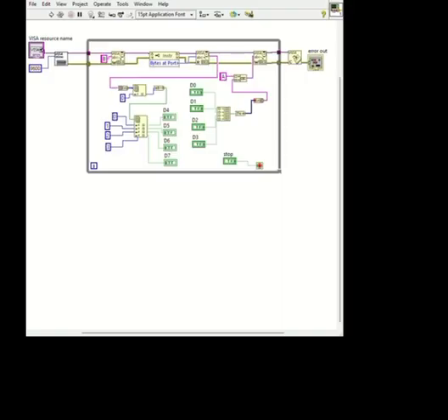To obtain communication in LabVIEW, specific blocks are used, such as the serial port, which tells us which port is connected to the Arduino and from where it will receive or send information. Then we have the write block, which sends the instruction to the Arduino so it is executed physically, and the read block, which receives the instructions from the Arduino so they are executed on the front panel.